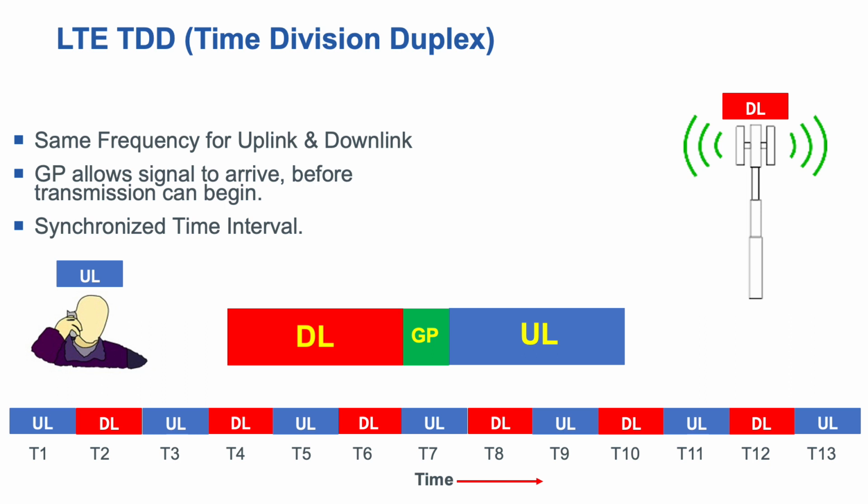It also requires some fairly sophisticated synchronization, as we are basically using Time Division Duplex. There's one slot for the uplink and one slot for the downlink. This technology, though, does give you some additional benefits, as the downlink, for example, can be customized. An additional period of time can be allocated to the downlink slot, as typically in many applications the downlink is going to require more capacity.